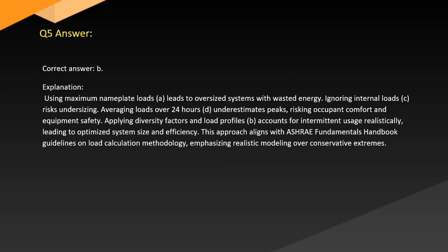Answer. Correct answer B. Explanation. Using maximum nameplate loads (A) leads to oversized systems with wasted energy. Ignoring internal loads (C) risks undersizing. Averaging loads over 24 hours (D) underestimates peaks, risking occupant comfort and equipment safety.